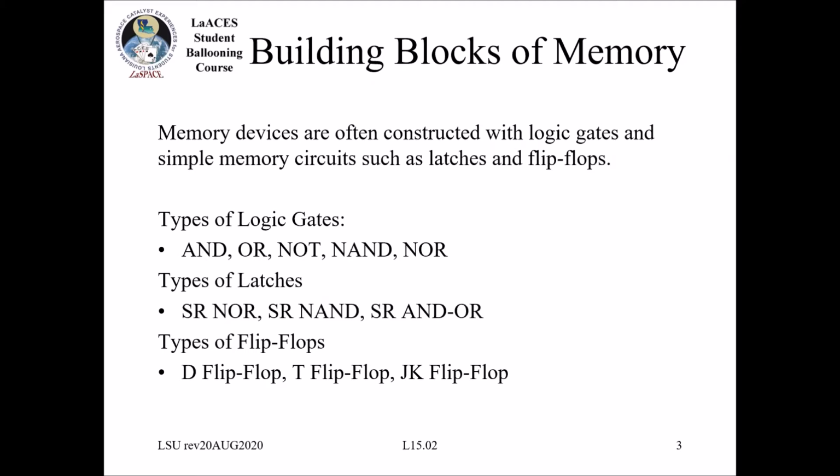These are actual pieces of physical hardware. So if I have an input to an AND gate, I have a positive 5 volts and a positive 5 volt signal going into it, the output will be a positive 5 volts. But if I have a positive 5 volts and a 0 volts in, it'll be 0. So they just work exactly like that.